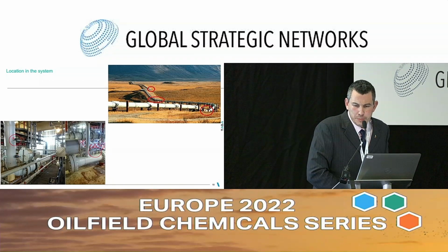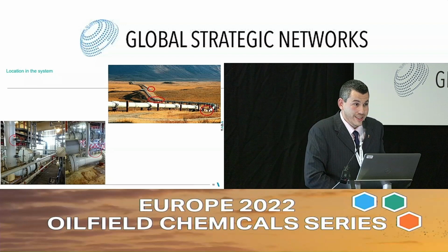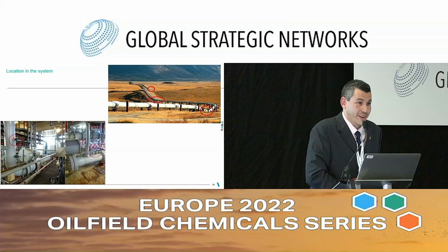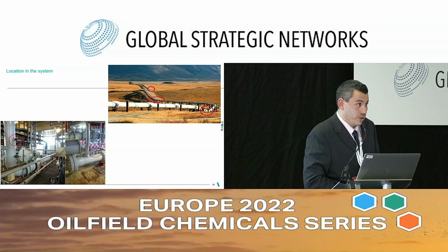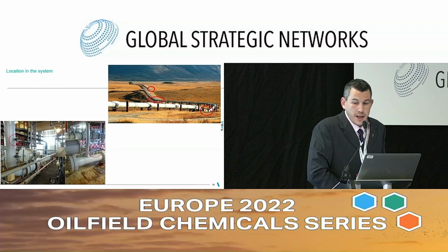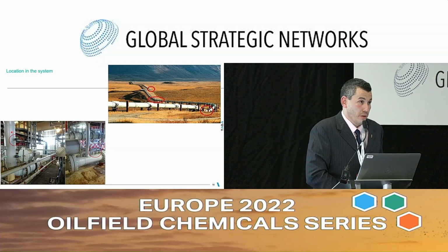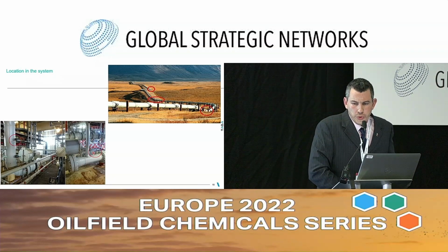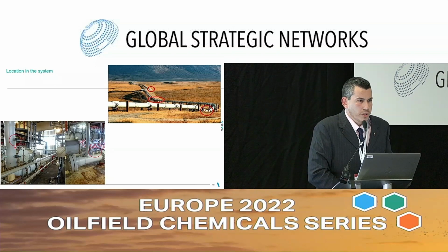With this slide, with this picture, I want to show you how corrosion coupons look in reality. They don't look like corrosion coupons. So that's why record keeping and proper documentation is so important. If there is a new technician or a new corrosion engineer coming to these assets and they don't know what's here, this could be a bioprobe, this could be a corrosion coupon, this could be nothing, just a cover. So we need to keep documentation up to date to make sure that we use our monitoring equipment as efficiently as possible. And I also wanted to show you a couple of examples that we need to keep a minimum distance between access fittings.